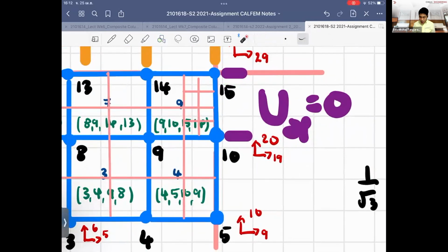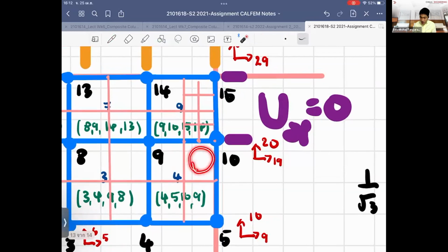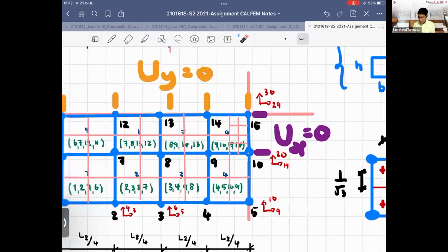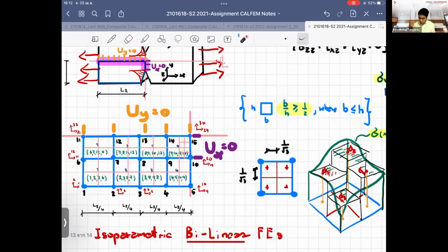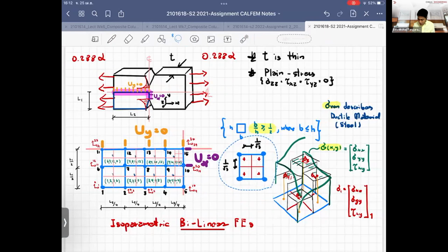So you might see that to make it compatible, when I discretize over these regions, it will make a node here. You see, it's clear, right? When we have the node here, and if we don't discretize the neighboring element, this element cannot be formed, because we have 5 nodes. If the 5 nodes come and match with the 4 nodes, we create a problem. The problem that we find for this 5 node, we call a hanging node, which we don't want to happen.